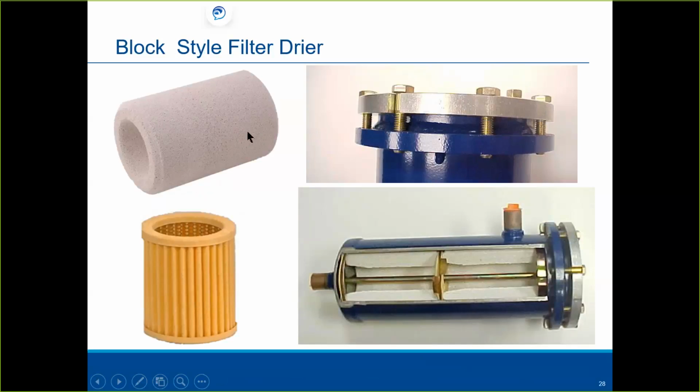Now, if you do your testing on your acids and it still shows acidic in there, obviously it's not one and done. We have to put a new block in there, and we might have to do this multiple times. Typically, one time is enough, but it's not set in stone. You have to keep testing the refrigerant after you remove this, okay?